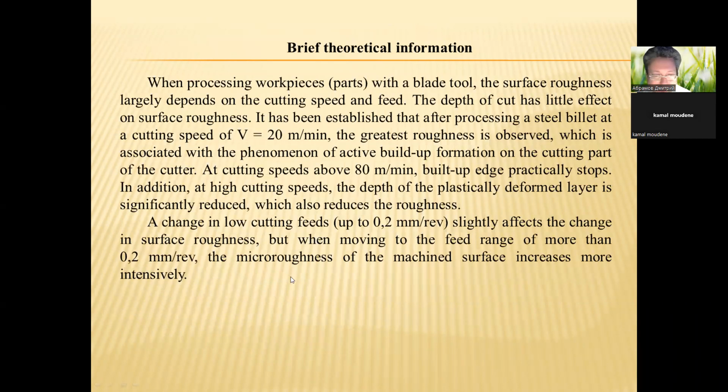Please write down to your notes brief theoretical information about roughness and about our laboratory work. When processing workpieces or parts with a blade tool, the surface roughness largely depends on the cutting speed and feed. The depth of cut has little effect on surface roughness.